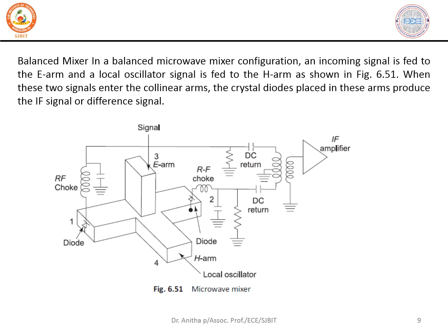And the other one, you observe, it can be used as a balanced mixer in a superheterodyne receiver. If you recollect the superheterodyne receiver, you have an RF, radio frequency, signal from the RF amplifier, and a local oscillator signal from the local oscillator. These two signals are combined in the mixer, and the output you get is the IF, intermediate frequency. At the output of the mixer you have the difference frequency and a number of components. Among those, the difference frequency will be tuned by the IF amplifier. The same configuration can be attained in the microwave region by using the Magic T.